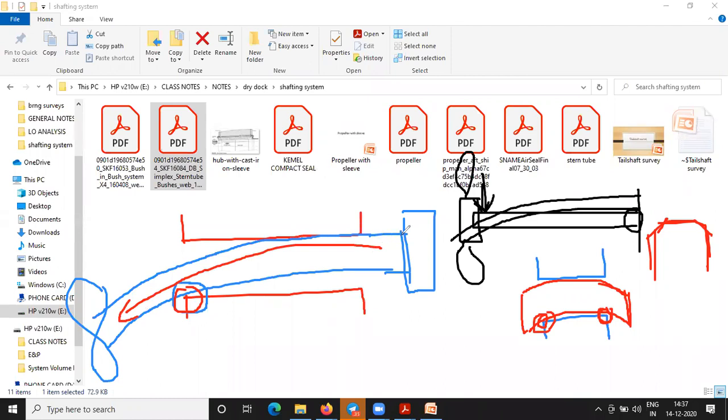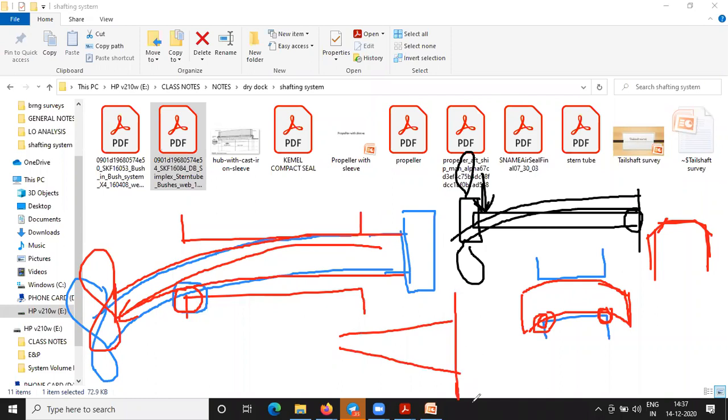So what happens? The shaft will now have a bend. Even if it is bent, since it has a taper, what happens? One thing, I'm reducing its weight because of making it taper. When I have the rod fitted at this point, and now I am having less weight, will it bend more or less than the previous? Less. Less than the previous. And also when it bends, since it has a taper and the bearing comes like this in actual condition, the edge loading is reduced or not?